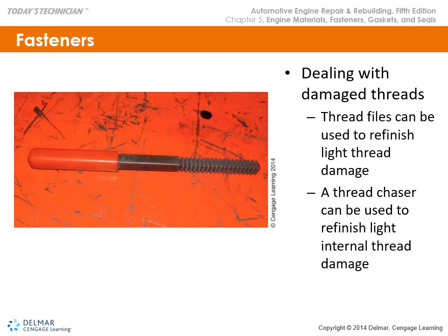Damaged threads can be repaired with this thread chaser that will allow you to repair some damaged threads rather than using a tap, because these will actually put just enough cutting on it to clean it up so you could reuse it.